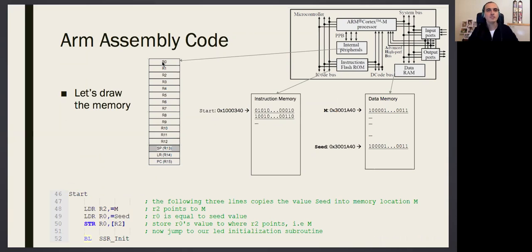What are the possibilities? The first possibility is, just like we've learned now, I can immediately put a value. Put FFF there. The second possibility is that I could be reading a value from another register. So get the value inside R4 and write it to R0. Since these registers are in this small box here, they are very close to each other.